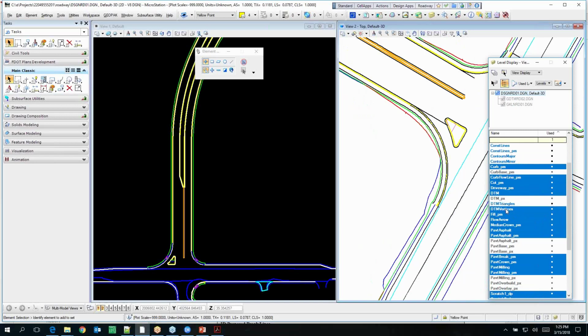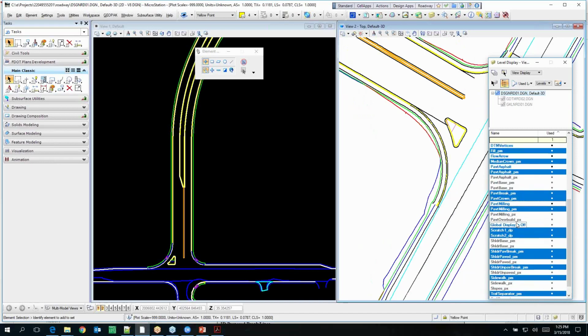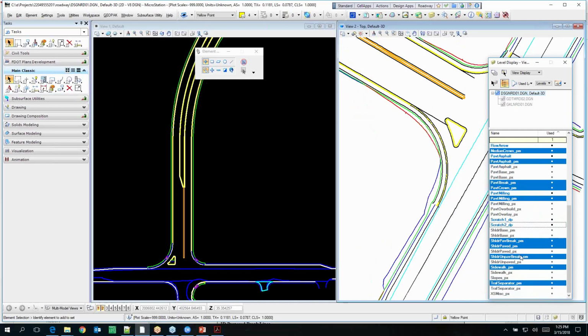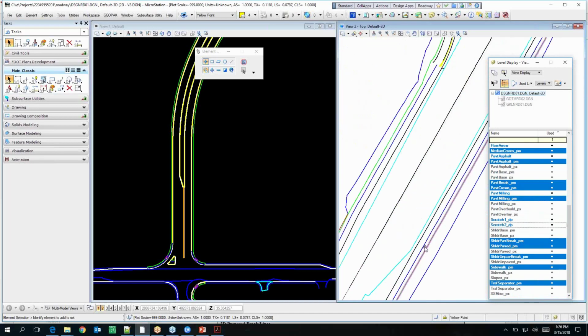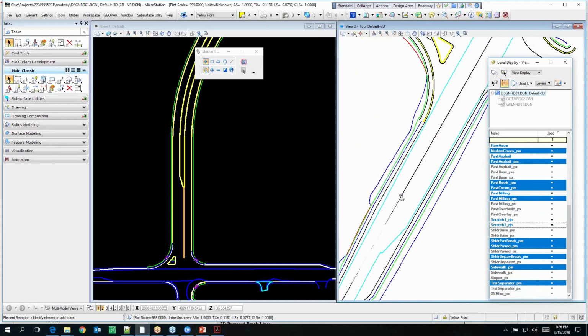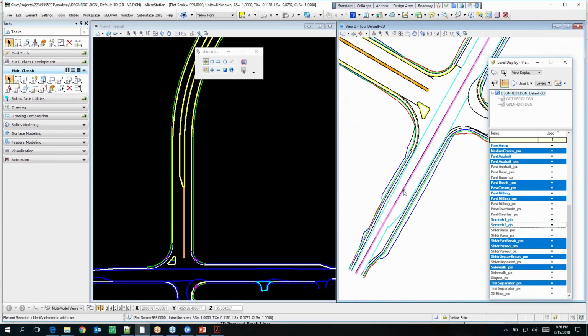And all you should end up with are PM lines that make up the top surface. So anything that's not PM should all be turned off. Scratch should be turned off. Scratch, all those, yep. Looks right. Then if you look at the 3D lines, it should look kind of like the 2D lines, only 3D, right? And there aren't any extra ones anywhere.